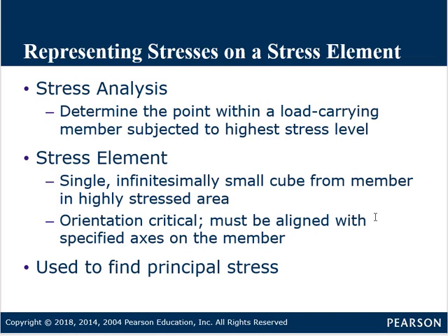Okay, next. For those of you who've had advanced strength of materials, we talked about an infinitesimal stress element. Okay, so stress analysis is where you determine the point within a load-carrying member that is subjected to the highest level of stress.